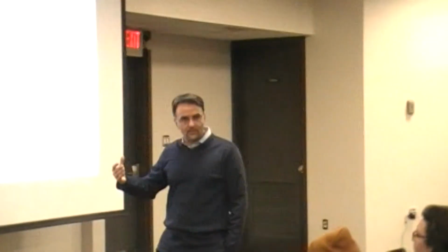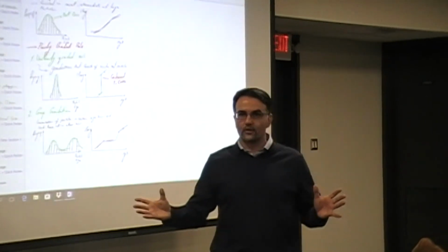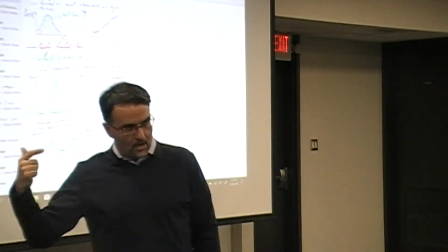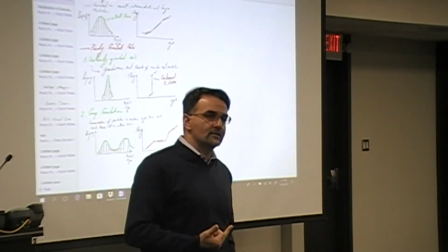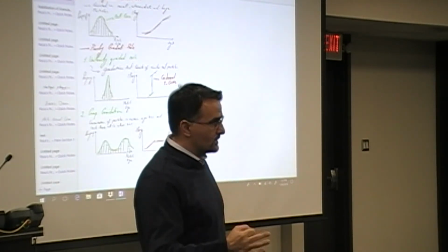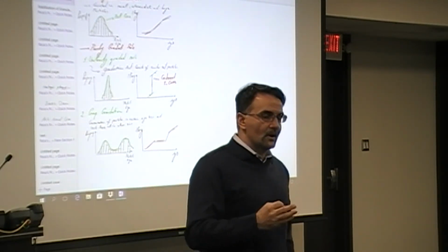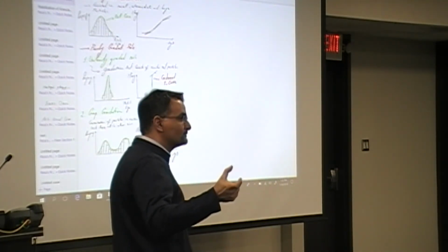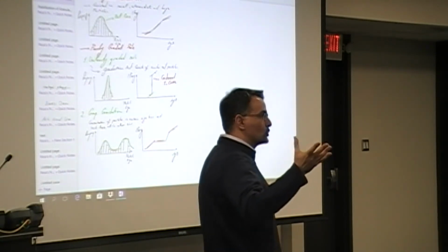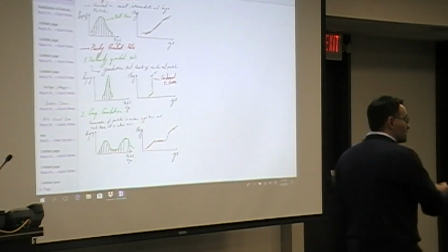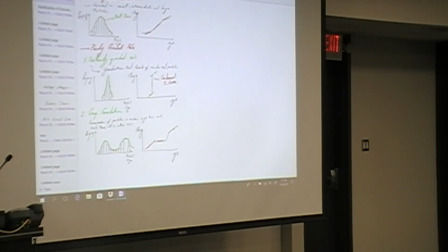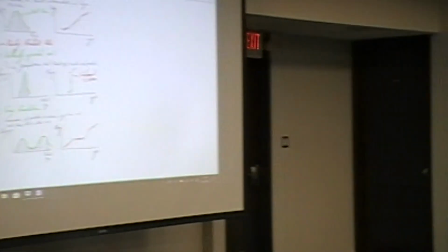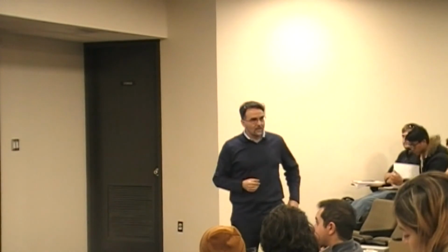Now, the second category that we had was poorly graded material. Under the poorly graded material, we subdivided it into two categories. Category one was uniform gradations, and the other one is gap gradation. One thing you have to be very careful about is that when we talk about uniform gradation, the word uniform has a positive connotation, right? When we say uniform, it means, oh, it's good. But figure out what it is good for. It's good for drainable layers, drainable systems, sand drains, the drainable layers at the toe of the dam, and all the other applications that we have for the drainage properties.